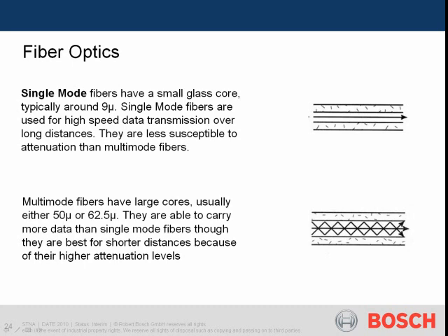Multi-mode fiber optic cable has a larger diameter core that is much larger than the wavelength of light transmitted, and therefore has multiple pathways for several wavelengths of light to be used within its fiber core. Multi-mode can be used for most general fiber applications, such as fiber to desktop or adding segments to your existing network. Multi-mode comes in two general sizes, 50 micron and 62.5 micron.